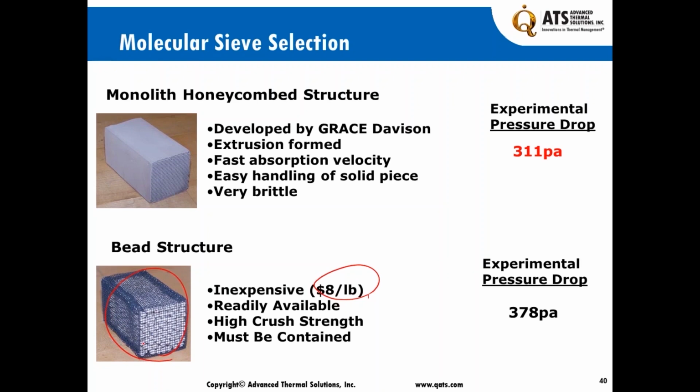But take note of the pressure drop, both experimentally obtained, and these do make a difference in your design depending upon the airflow rate requirements that you have, as I showed before with respect to the system curve and the pressure. So every resistance across the path of the flow, you want to be able to minimize it in order to make sure you get the best. And then applications, which application gives you the most effective value for your process and your work.